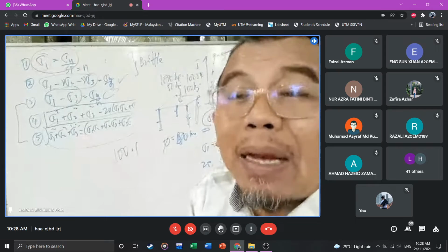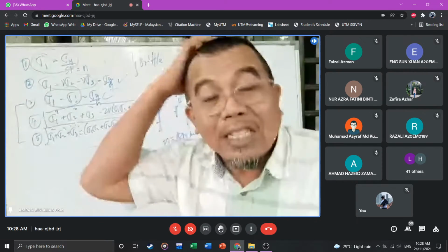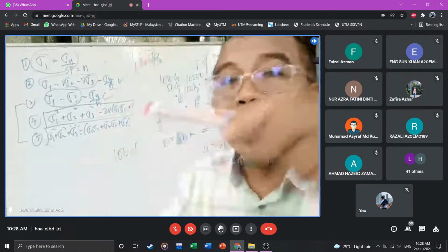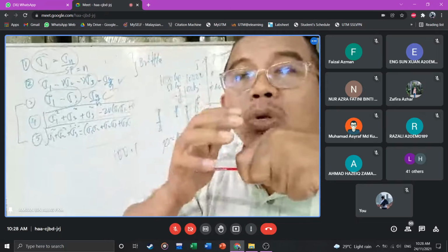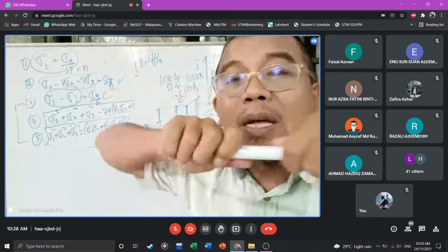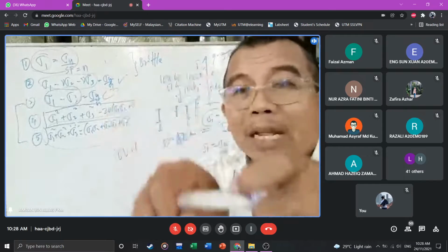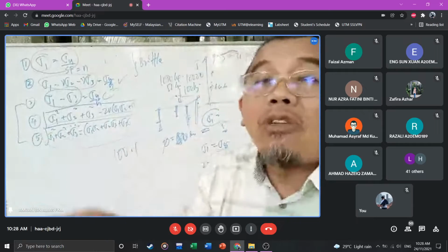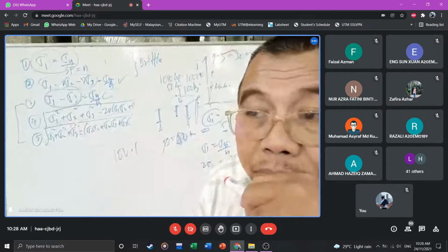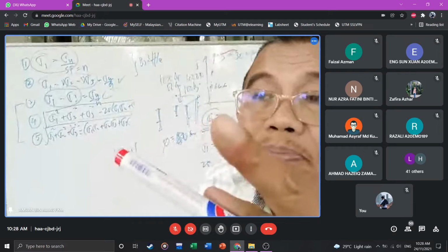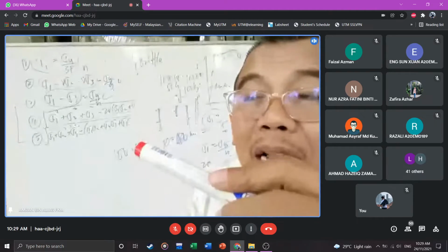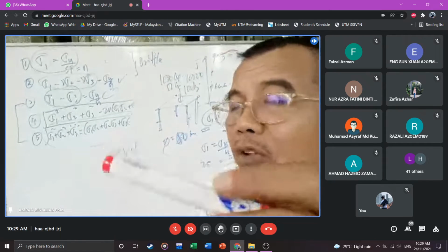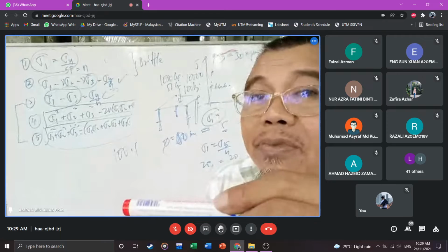Especially mechanical engineers. So what do engineers do? Understand this again, it's very important. This is the size of the product that you want to make. Whether it's torsion, a bending moment, or tensile or shear, you can convert it into stress and find the maximum stress. The stress you calculate only in the XY direction. 20 degrees from XY, you cannot calculate. You have to do the analysis.